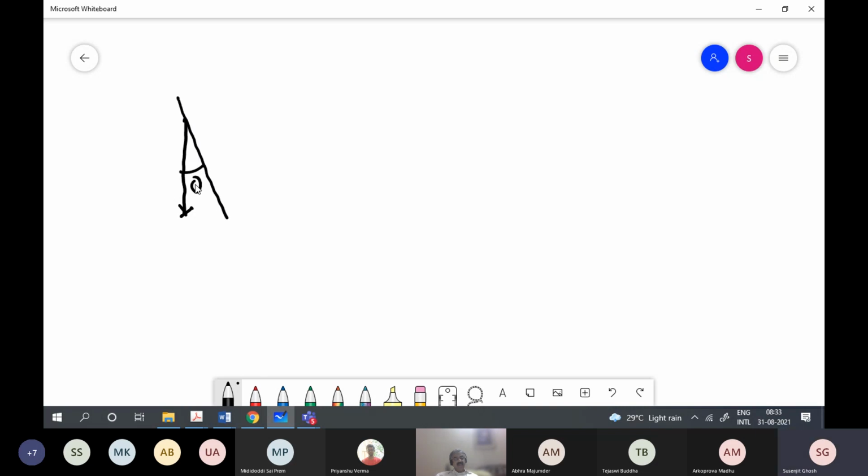This is theta. The maximum value of theta can be 0.1 degree. So if you are applying this inside the sensor, you don't know. Imagine that the sensor has a box. On the box, x-axis is marked on top of the box, but inside the box, the sensor package is misaligned. It is not aligned with the marking on the box.